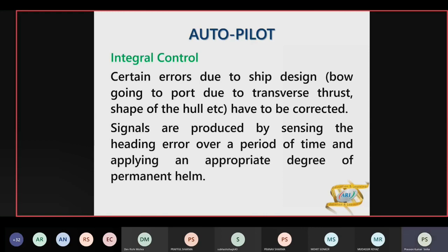When the propeller is turning, she is not only propelling the ship forward, but the pitch angle of the blades are also pushing the water sideways. In doing that, the stern starts to go in opposite direction.